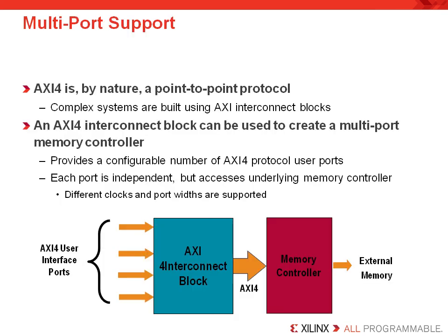So as we mentioned, the AXI 4 is by nature a point-to-point protocol, and this is best supported with complex systems, and they're often built using the AXI interconnect blocks. Now an AXI 4 interconnect block can be used to create a multi-port memory controller, and this provides a configurable number of AXI 4 protocol user ports. And each port is independent but accesses the underlying memory controller. So it does support different clocks and port widths in its application. Now the AXI 4 interconnect blocks are provided by Xilinx, again, as part of the IP from the EDK toolkit as well.